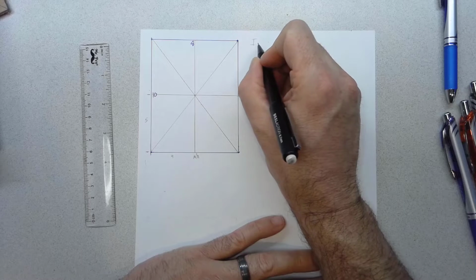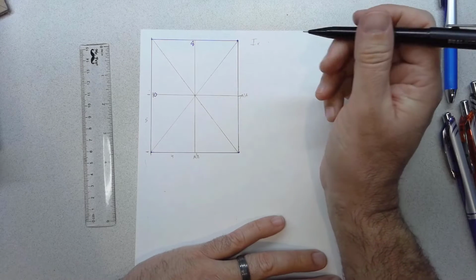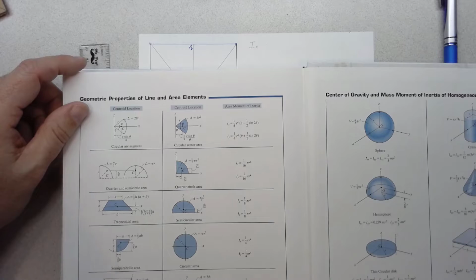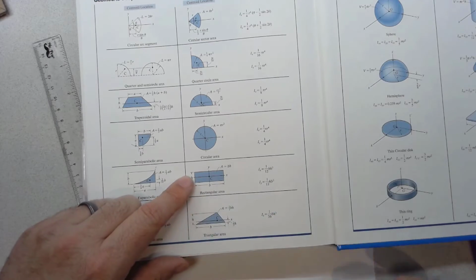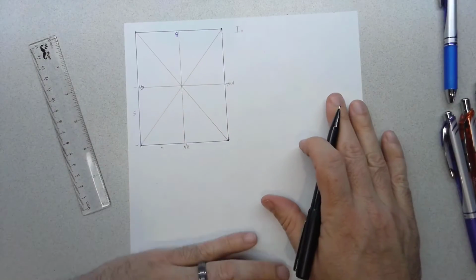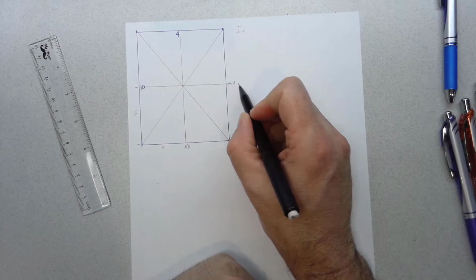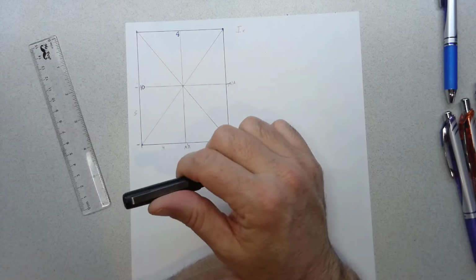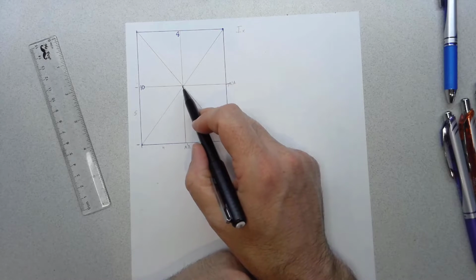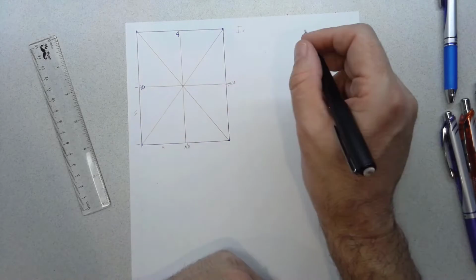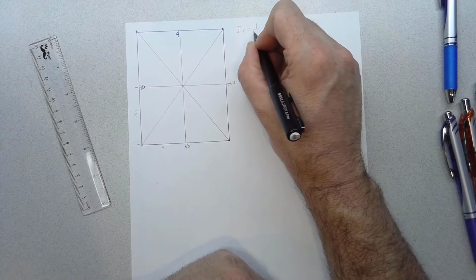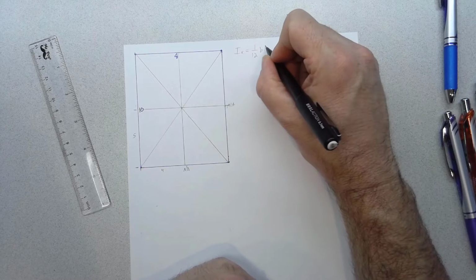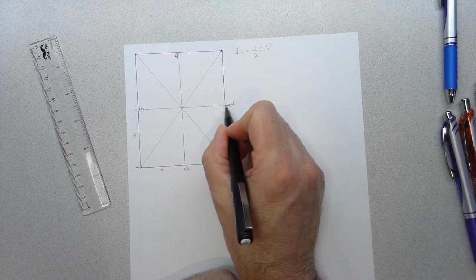When we say Ix, it's always about the centroidal axis. So again, looking back at this table, the moment of inertia for this rectangle is 1/12 bh cubed, and that's about bending about the centroidal axis. And so we just covered how to find centroids. We're not going to do that again. But another key idea is the neutral axis of a beam is always located at the centroid. So that's why we focus on centroids first, is we need to know where that centroid is, and that's where the moment of inertia is about, the default equation. So when we say Ix equals 1/12 bh cubed, this I is about this neutral axis.